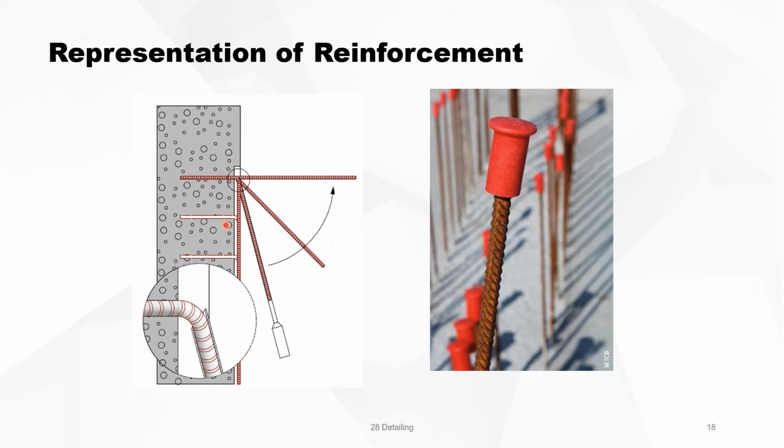This is a typical element for walls where you can put rebars in it, close the shuttering, and when everything is poured, you open the shuttering and you can pull out the rebar by means of an extension tool where you can put another rod in it and you can pry it over.